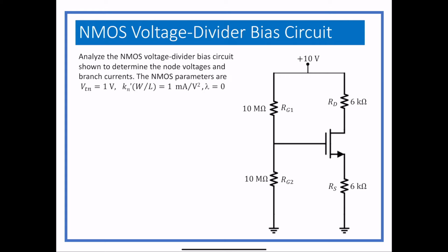The analysis starts with the input side, and we need to know what the voltage at the gate is. And the nice thing is, because there is no current flowing into the gate, it's just a voltage divider, literally. It doesn't have any weird other things going on, and when we get to bipolar junction transistors, this will not be the case.